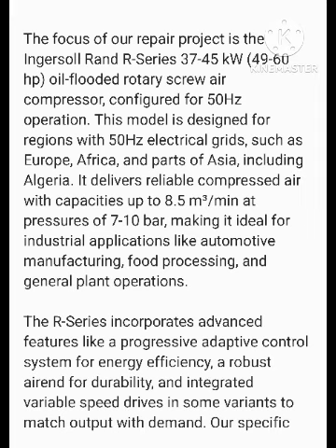This model is designed for regions with 50 Hz electrical grids, such as Europe, Africa, and parts of Asia, including Algeria. It delivers reliable compressed air with capacities up to 8.5 cubic meters per minute at pressures of 7 to 10 bar, making it ideal for industrial applications like automotive manufacturing, food processing, and general plant operations.